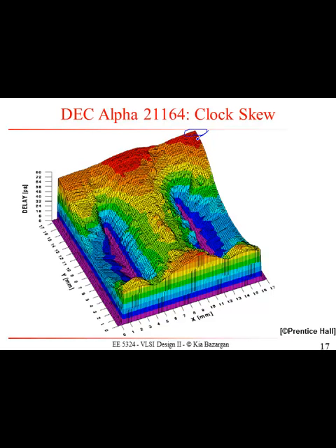If you look at the floor plan, you had some of the logic that does ALU operations and stuff here. And then this part is part of the cache, and you have cache controllers here and so on. So none of these ALU units, for example your adder unit, is going to directly connect to your cache line and get values from that memory, right? The memory is going to first go to the memory controller, and then you have your sense amp or whatever that you need to have, and then going from there to there.